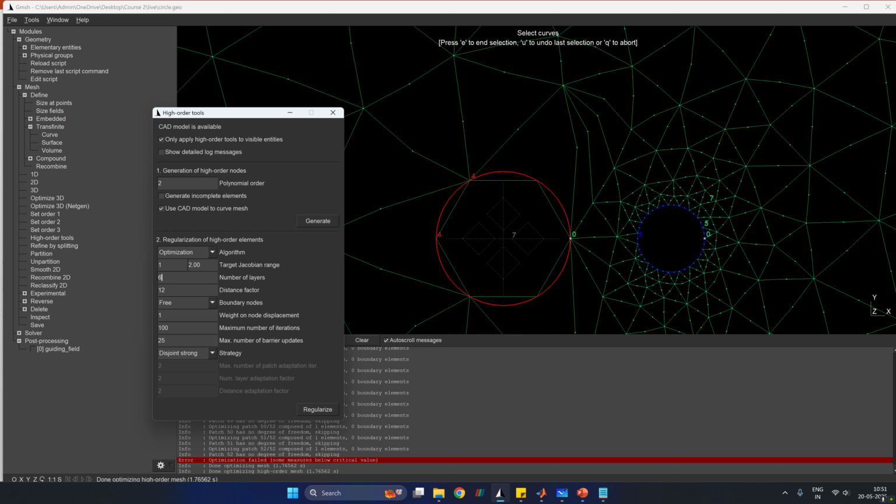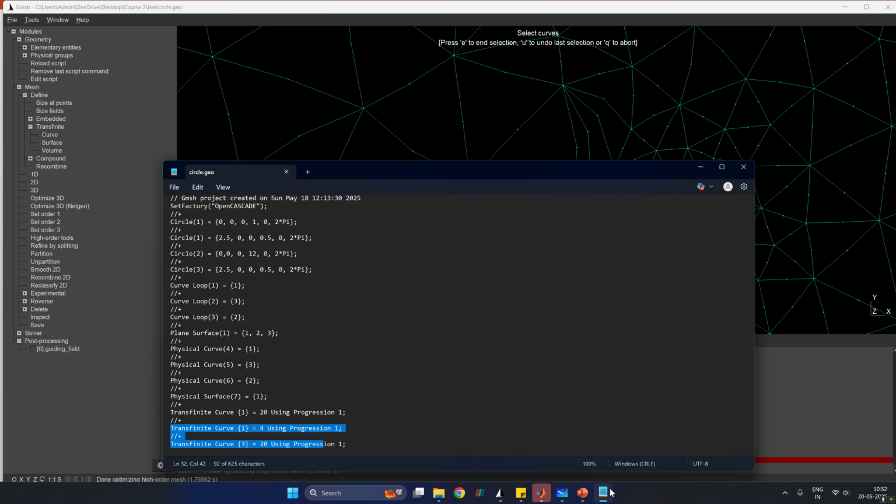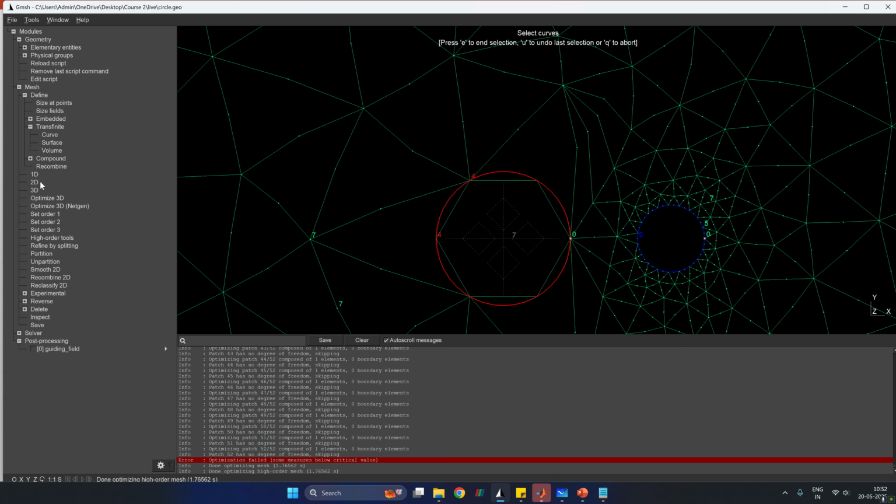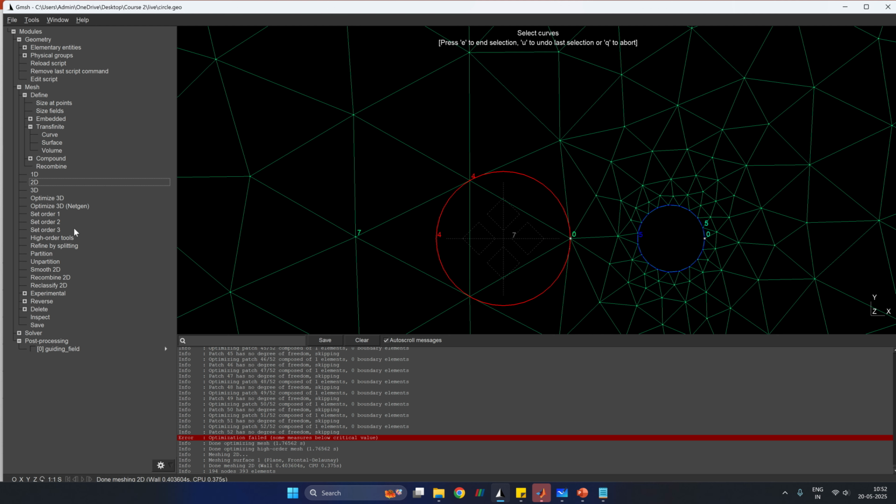So this is really important for turbulent flow modeling, where you have to define a wall function, and there the number of layers and all of these other factors will become crucial. But in this case, really we can go with the default mesh, and let's just do that. So we can have a look at these points for mesh generation in more detail in the next course, which will be about Navier-Stokes modeling. So let's just define this mesh, and